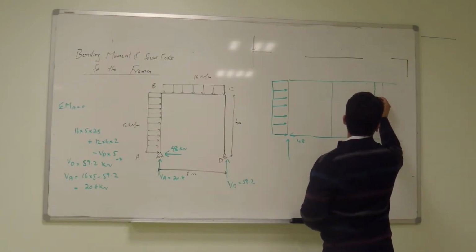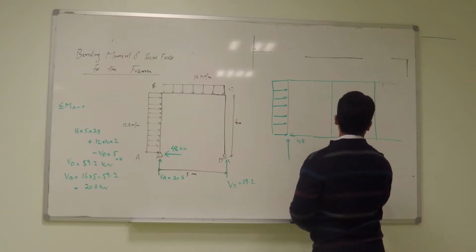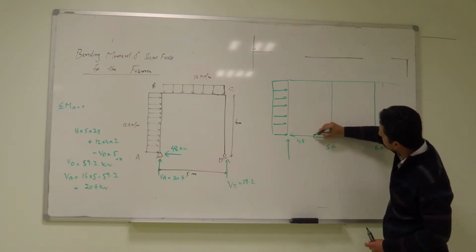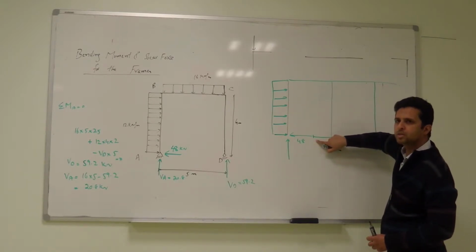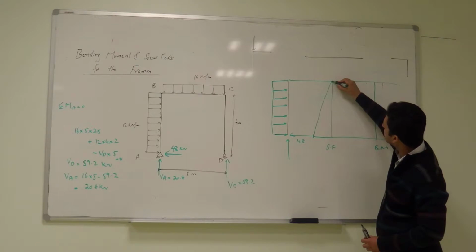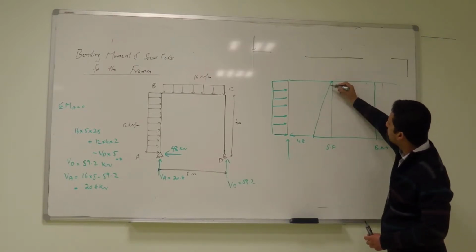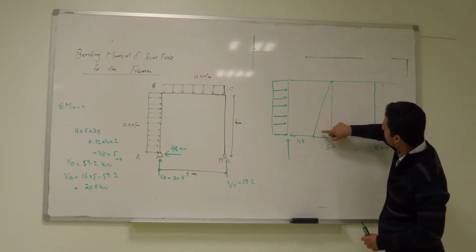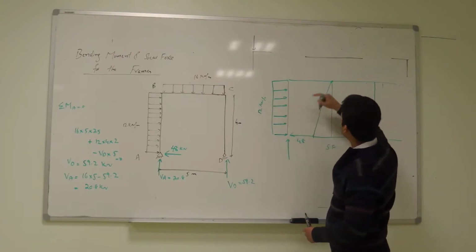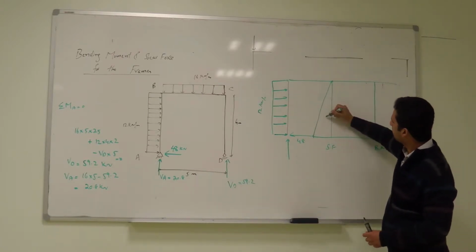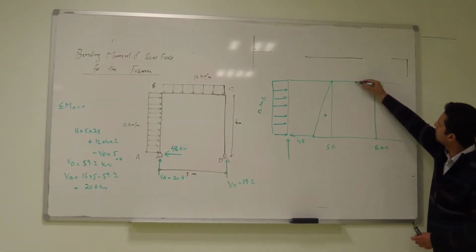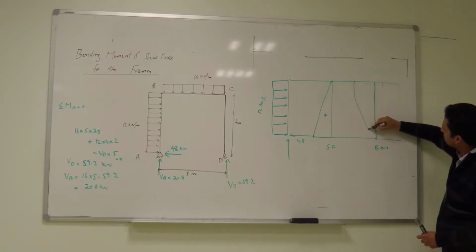And here there will be the bending moment diagram. Shear force and bending moment. So you have positive shear, 48. And it will go down to 0 here. If you see your member, it will be in equilibrium: 48 minus 12 into 4, it will be 0 here. Positive. And now the moment from here will be 0. It will be something like this, a parabola.